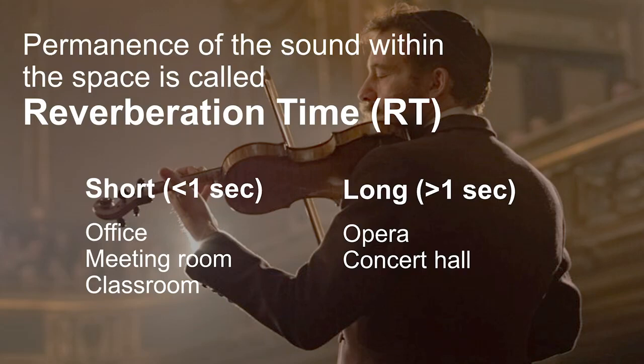So you can see there is a very fine and fragile limit between these values, and actually that's the beauty of acoustics, because there is no strict rule what is good and what is bad. But our general idea and our target is to make the speech intelligible and to make the music strong and clear. And we use reverberation time as the convenient way to express and quantify that.